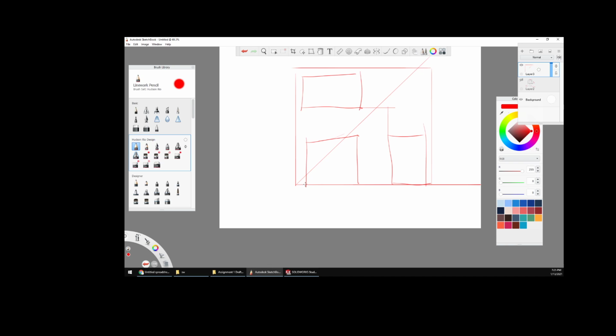And what you can also do, if you do this right, which I didn't do, is when you do the side, let's say you've got grooves in here. Well, in order to make sure you got your grooves right here, you do your light line here. And that guarantees that your grooves are in the proper spots. So that's kind of where that came from and the reason why you have that top front view.